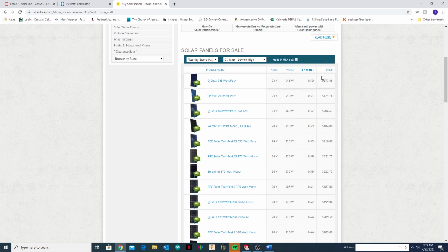Anyway, onward. So now let's calculate how many panels we need for going east. Well, for east, we got 8.4 kW. So we're going to put 8,400 watts divided by 345. That's the size panel. And we're going to need 24.34 panels. Again, we always round up. So we're going to go 25 panels if we're facing east.